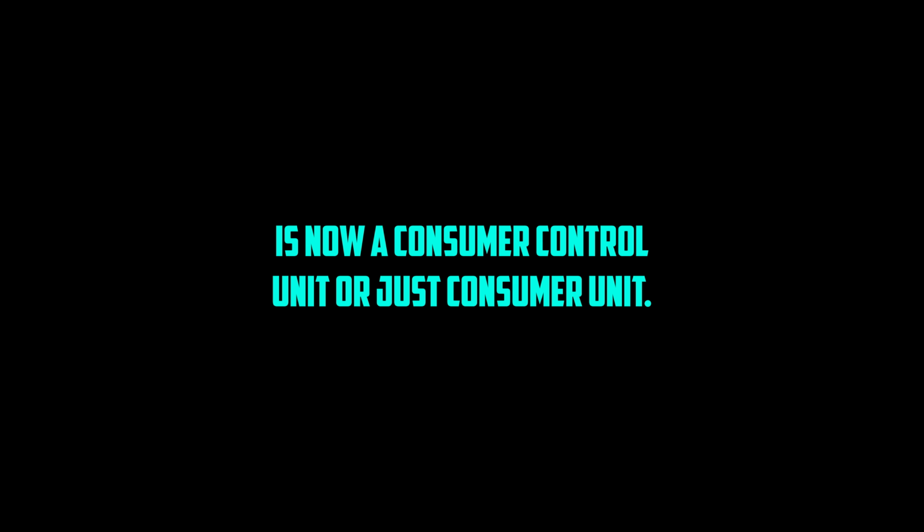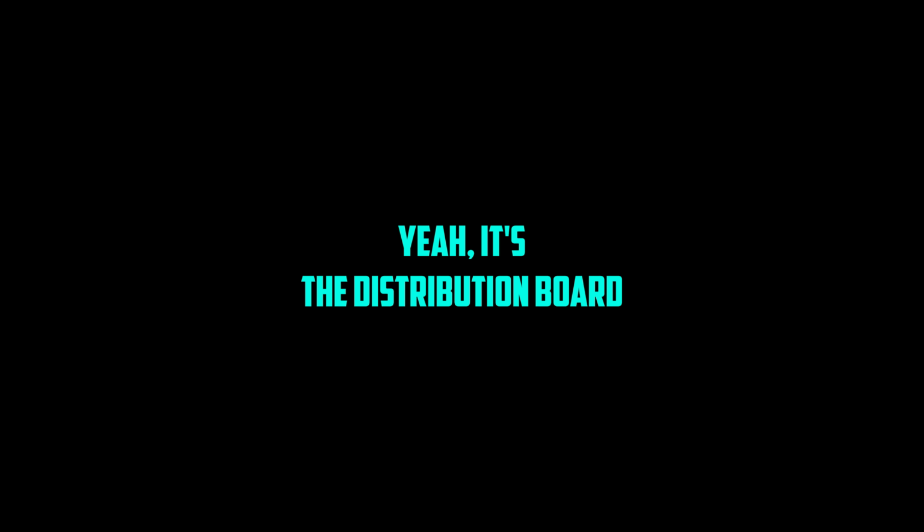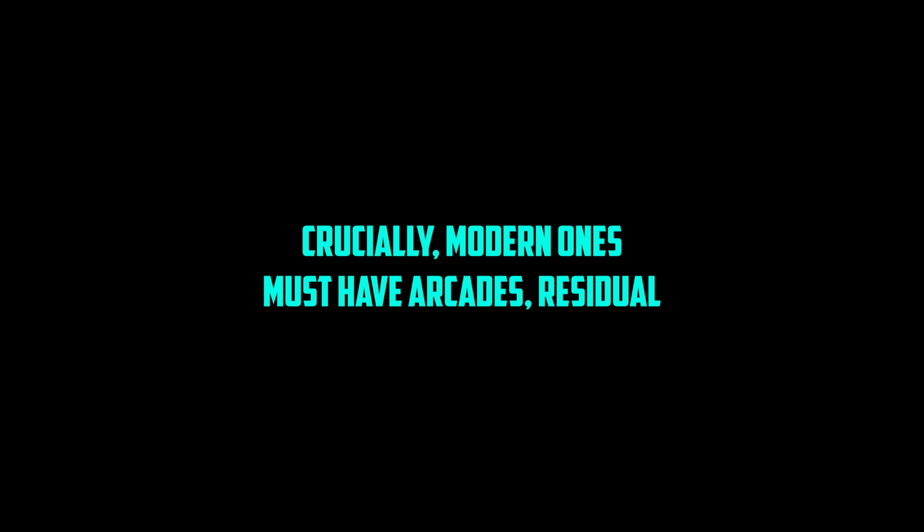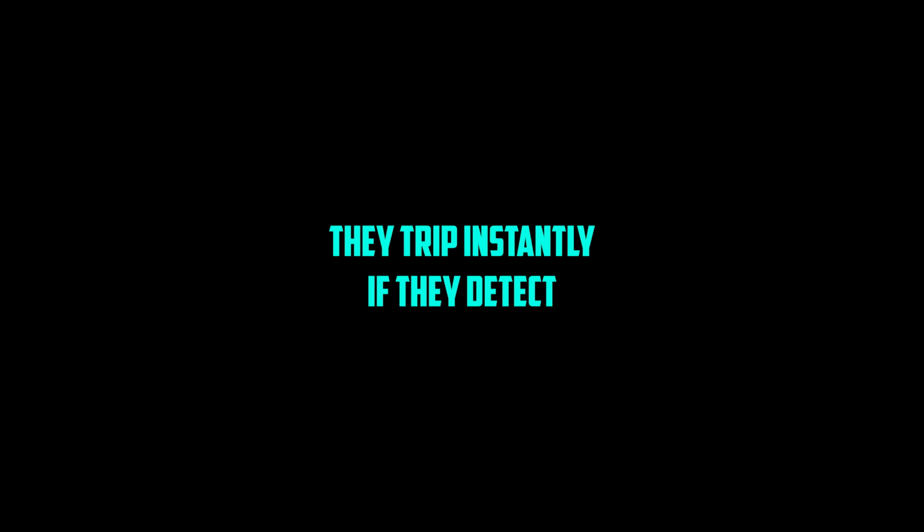Electrical supply. Safety first, always. Top priority, proper earthing, preventing leakage, stopping fires. External meter boxes are preferred now for easy access for readings or emergencies. And the fuse box is now a consumer control unit. Or just consumer unit, yeah. It's the distribution board. Has the main switch, bus bars distributing power to individual circuits, and protection, either fuses, older, or MCBs, miniature circuit breakers. Crucially, modern ones must have RCDs, residual current devices, protecting circuits, especially sockets, for shock protection. They trip instantly if they detect tiny leakage currents to earth.